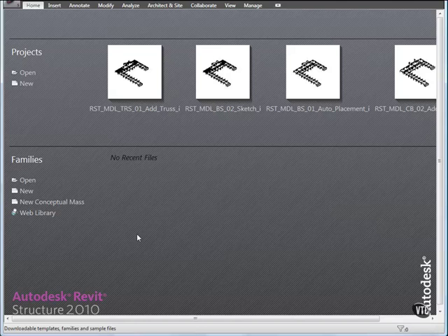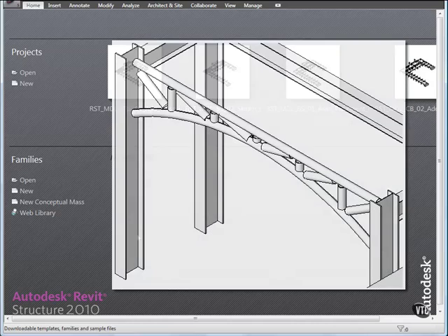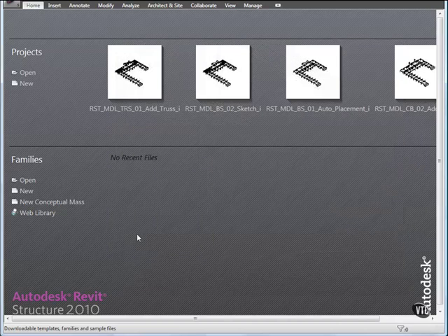In this lesson, you will create a custom truss by changing the properties of the standard truss, creating an arc for the bottom chord. Then, you will save the custom truss to the framing library in Revit Structure. You will also copy the truss to the opposite side of the entryway roof frame.